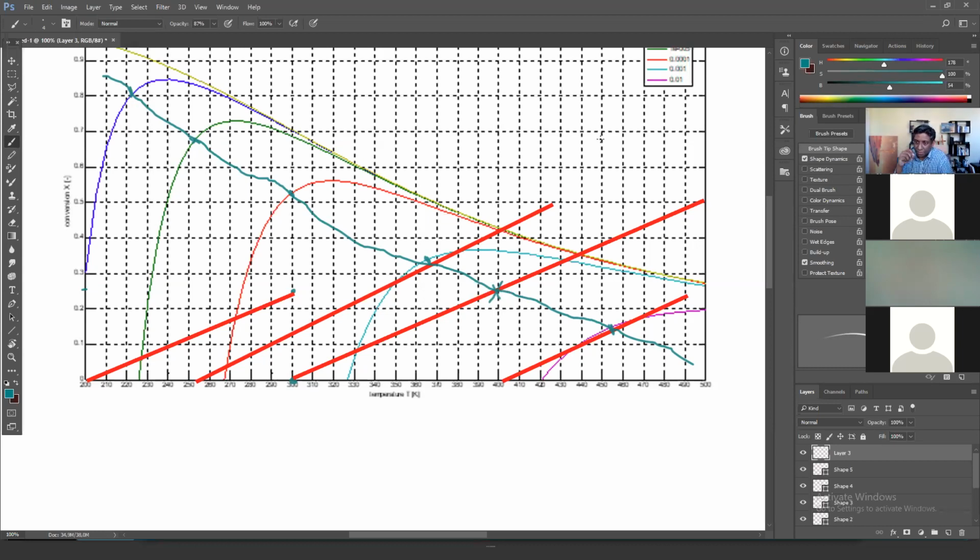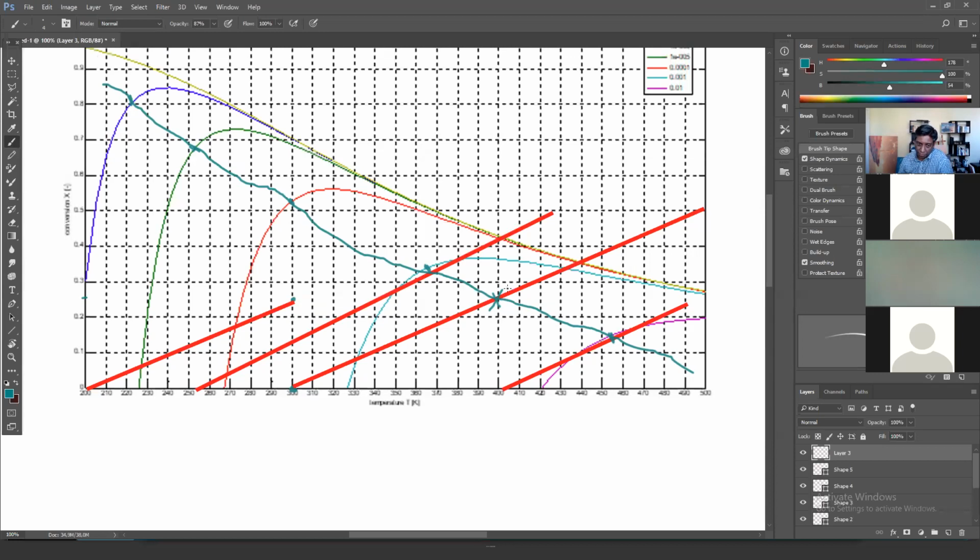So that's how we can cleverly estimate the region where we've got the high rate line, the high rate point. And we can say, well, if I operate on this point, then that's going to be the best possible reaction rate I can accomplish. So starting at a temperature of 300 Kelvin, that's the best choice for me. If I go any further, I'm going to get lower reaction rates and hence bigger reactor volumes.